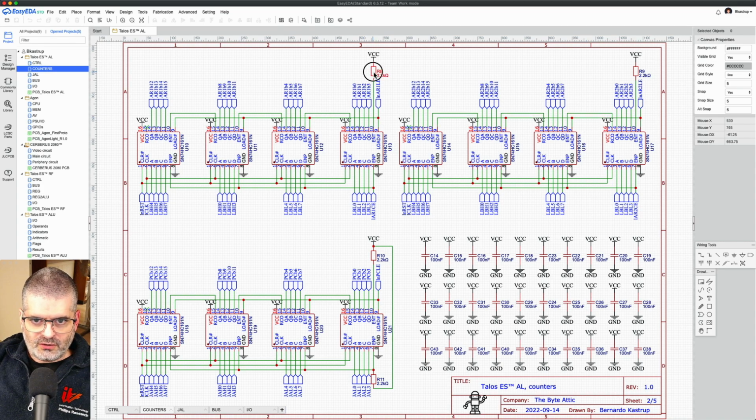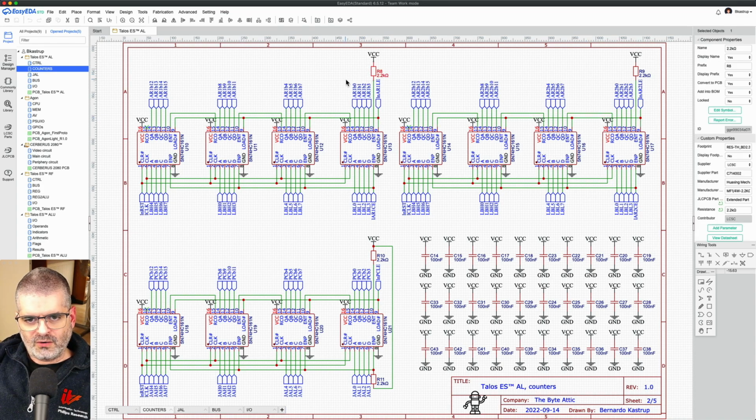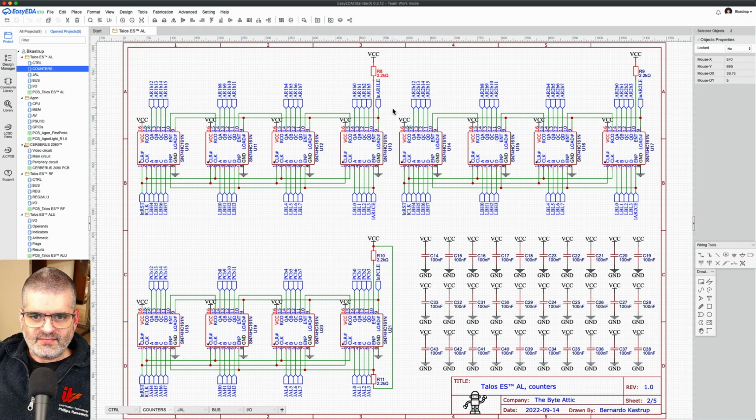I'm using a little resistor of 2.2k ohm in series with VCC, instead of putting VCC directly on the pin. The input impedance of these pins is very high, so there will be very low current draw anyway. Normally we use an in-series pull-up like this when the pin is not only an input but an I/O. In other words, the pin can be used for the chip to receive some information from the outside, but also for the chip to put out some information.